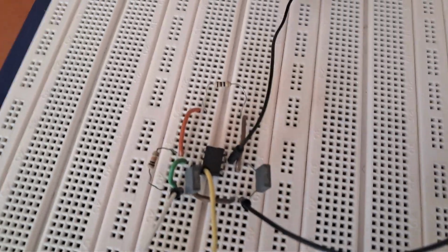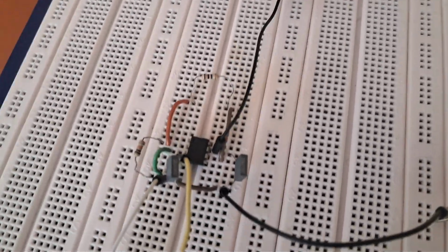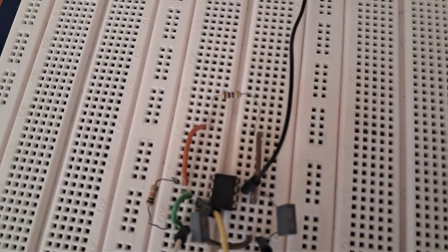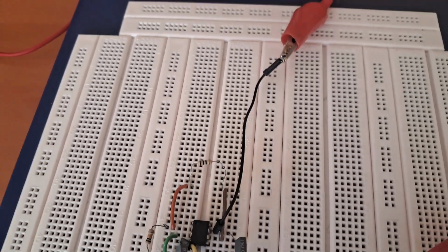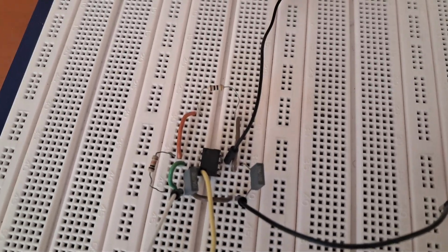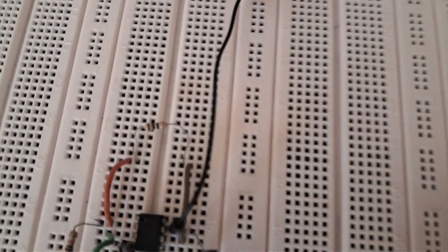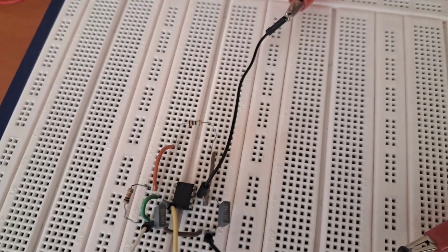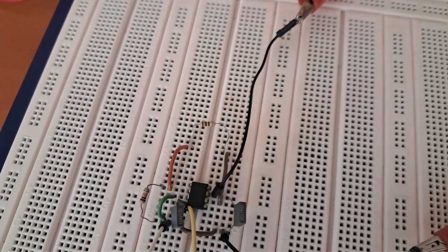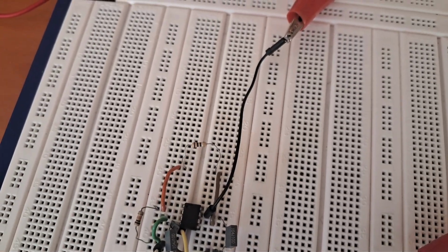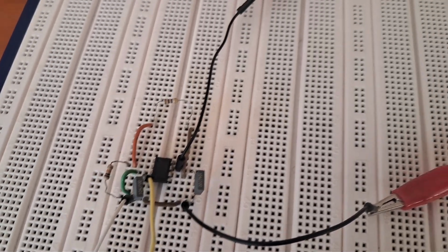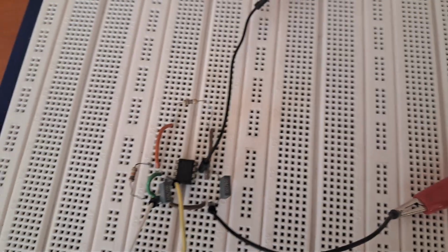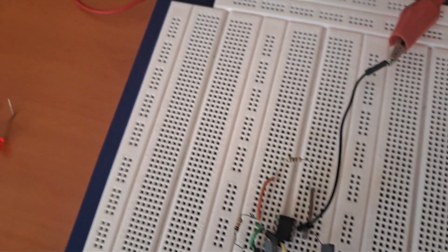To be able to measure the offset voltage, I constructed a basic amplifier circuit. I used around a 10K resistor, and I had my feedback resistor from the previous setup. Here the gain is around 1042. So I'm gonna measure my output voltage and divide it by this gain to find my offset.